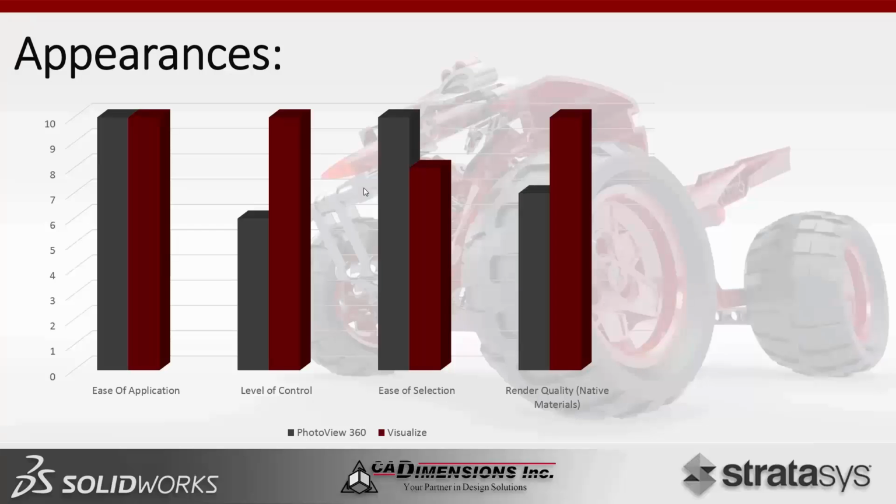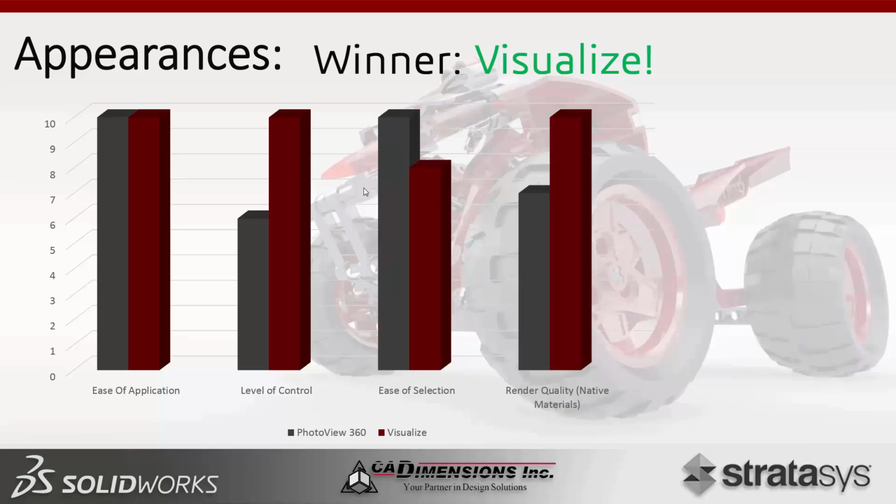All right, so for appearances, this one varies a little bit more. I'm going to give the winner to Visualize in this category. Ease of application is the same in both. Drag and drop, both are drag and drop. I typically apply my appearances in SolidWorks and then I pull them into Visualize. Sometimes I'll make some tweaks because I like the Visualize appearances better oftentimes, but for the most part, I will apply those. The process is the same, and drag and drop application works very well in both cases.